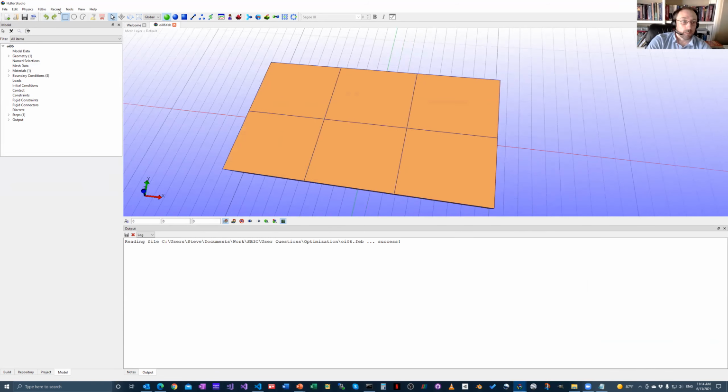Now, it doesn't support all these different objective functions, but at least you can generate a template that you can then customize to your specific needs. So you would go to FEBio, generate optimization file. That takes you through a wizard where you can set the control options. So it's Levenberg-Marquardt or constrained Levenberg-Marquardt. There's also a Powell method in FEBio and a scan method, which does a parameter sweep, but you'll have to edit the file manually for that. So let's just leave that for default.